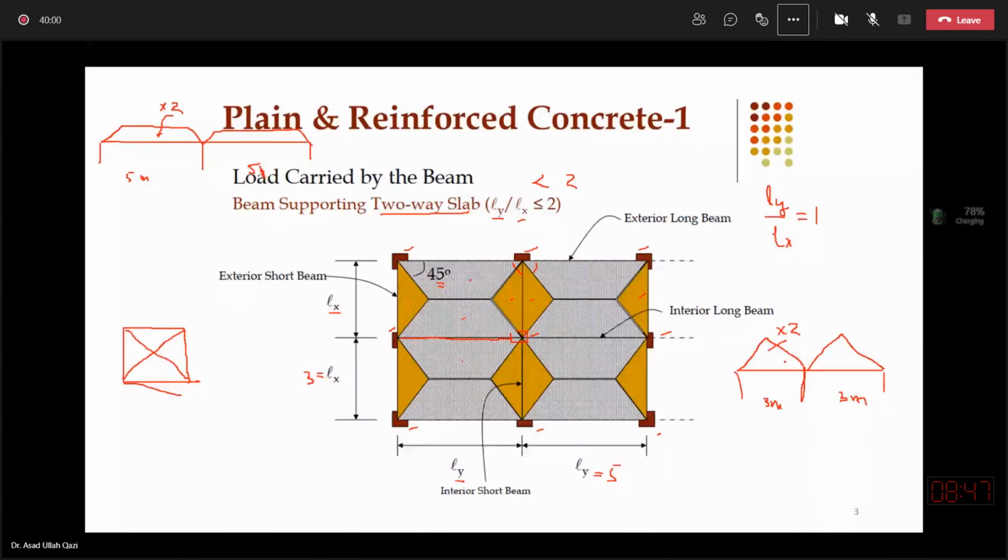Now here the problem is a little tough and tedious, because you need to draw the bending moment diagram for a beam which is subjected to triangular load or trapezoidal load. And if end conditions are simply supported, again the mid-span will have the maximum sagging moment. So the mid-span moment ordinate is important here. Now it is not WL squared by 8. So you need to write the equation, and then with a little more effort, you will get the mid-span moment.